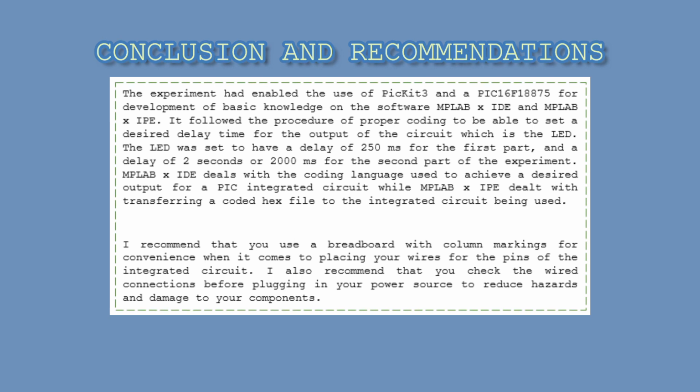I recommend that you use a breadboard with column markings for convenience when it comes to placing your wires for the pins of the integrated circuit. I also recommend that you check the wired connections before plugging in your power source to reduce hazards and damage to your components.